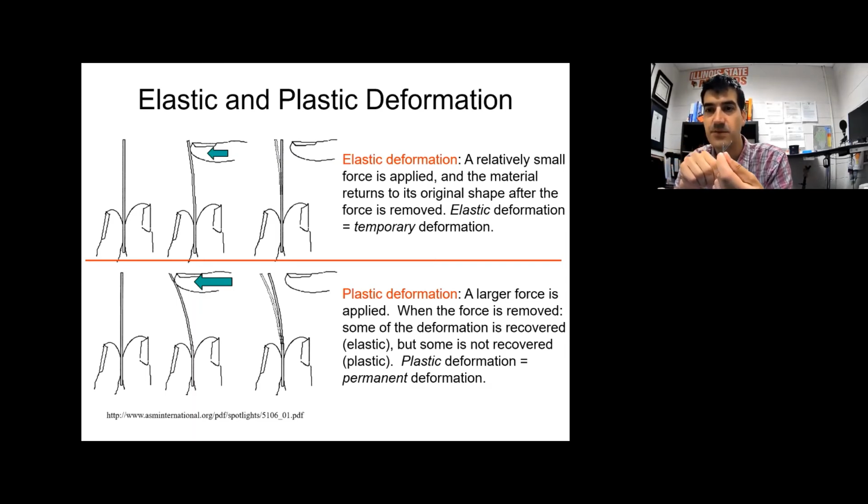I was watching, but it wasn't real obvious. When I deformed this and I got plastic deformation, then when I release that, you actually do get the elastic part of the deformation back. It does spring back a little bit, not very much. Only the portion of the deformation that was elastic springs back. But all of the plastic deformation, you don't get back. It stays in that position.